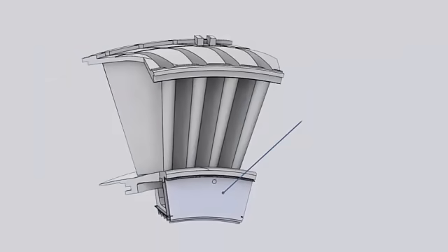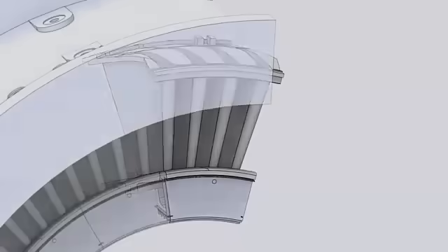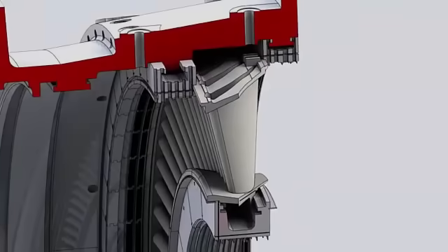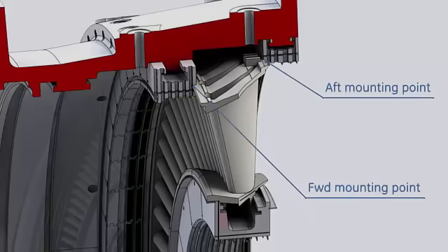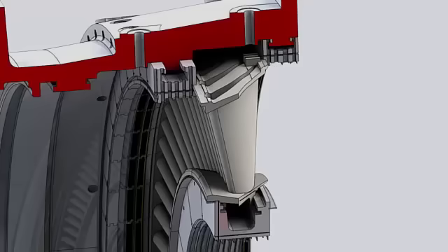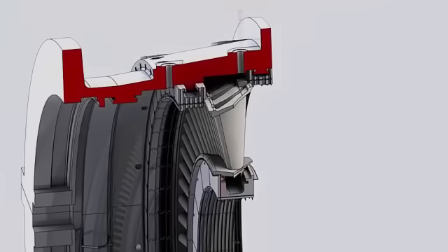A diaphragm segment is also attached to the inner sidewall of the nozzle. The third stage nozzles are not air-cooled. These segments are installed to the stator in the same manner as the second stage nozzle. The third stage nozzle is supported by the second and third stage shrouds. The nozzle segments are held in circumferential position by radial pins from the turbine shell into axial slots on